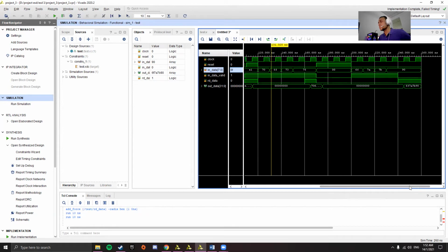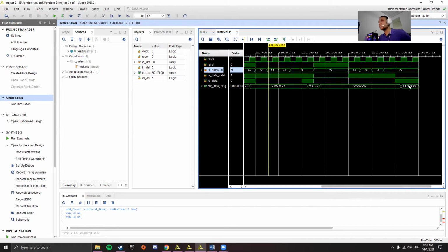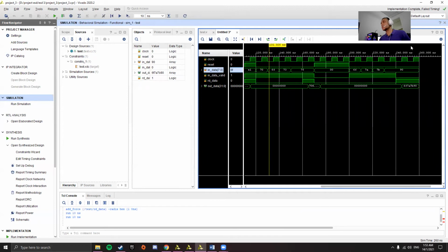So why is the output produced 4 columns combined into one? It is because when we enter the input, the one input is determined by only 8-bit. So if we demand to show the 32-bit, FIFO generator will combine 4 inputs together, 8 times 4 equal to 32, and will produce the output, which is 4 columns combined to 1.